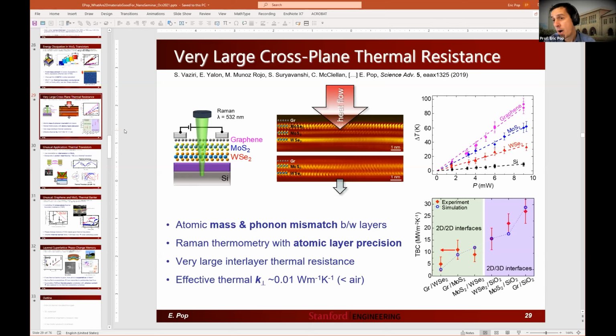I think you're absolutely right. This heterogeneous integration, and I don't have slides here, but even Intel has done some layer transferring of germanium films over a wafer scale, which I thought was very impressive. And so, if Intel and IMEC can do it at 300 millimeter wafer scale, I think there is some promise here. I don't know what the reliability or the yield is for such layer transfers at that scale. But I completely agree with you.